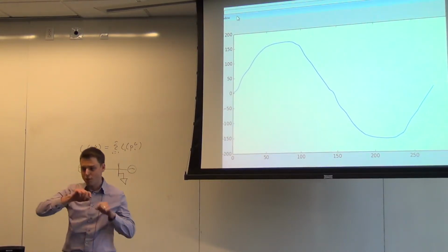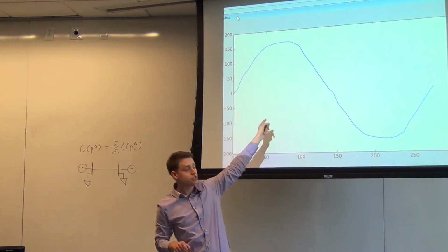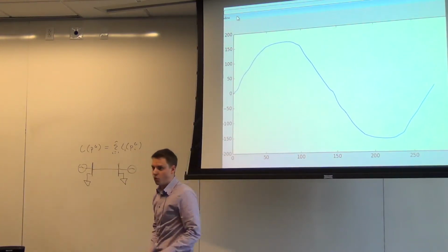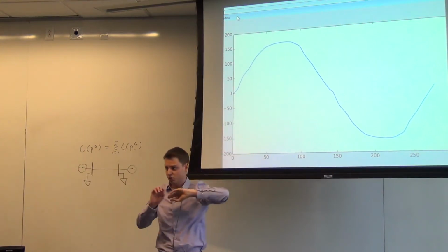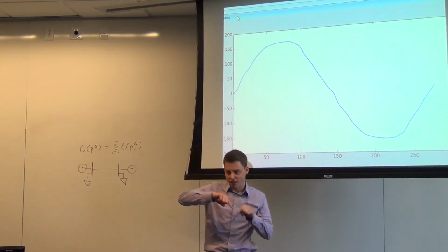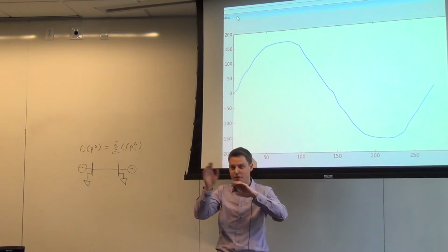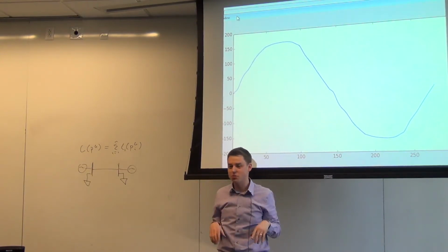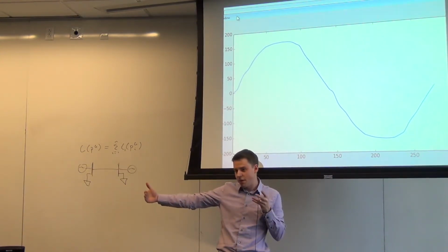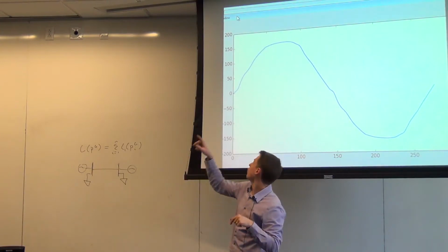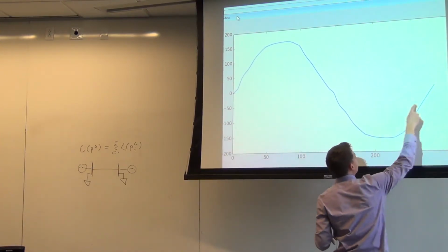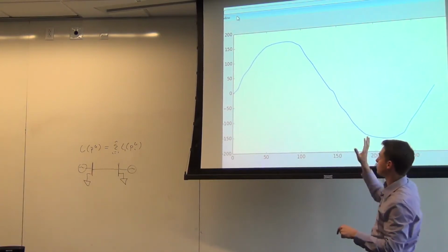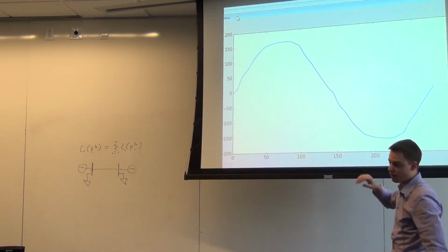And what I'm doing is I'm reading the voltage. This is the actual voltage that you see in the line here. I'm reading it, and I'm just finding the part where it crosses 0 and plotting just that part so it's aligned every time. If you just plotted the raw signal, it would look like a sine wave, but you couldn't really tell when it was. So I'm reading a certain amount of data, looking for times where it crosses from negative to positive going that way, and then again happens here, and I'm plotting it in that range. That's why you see a little bit of jitter in this plot here.